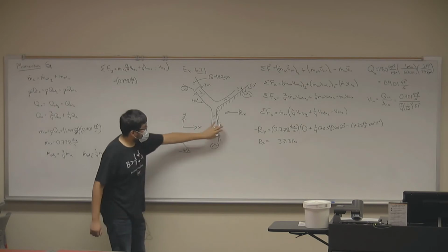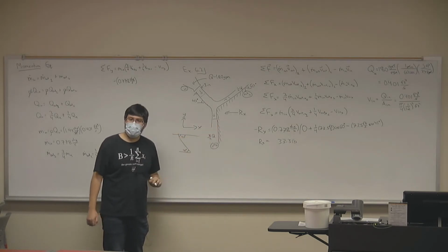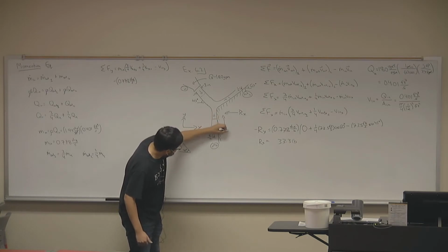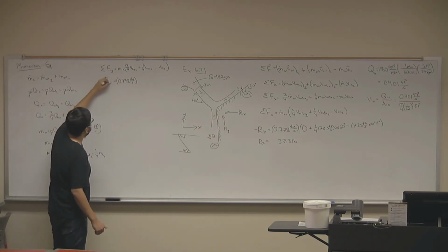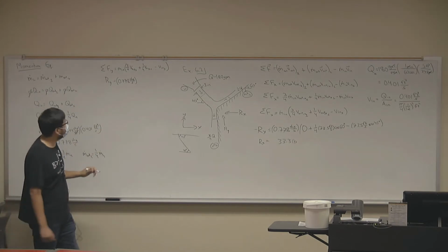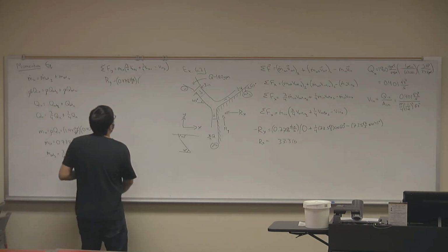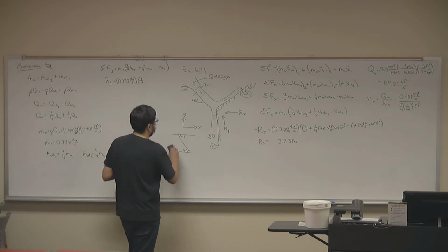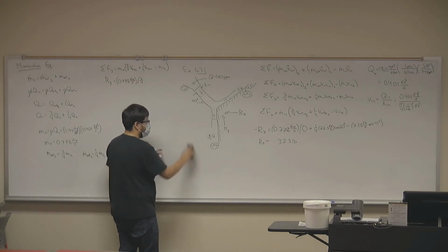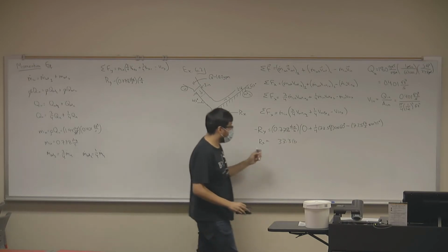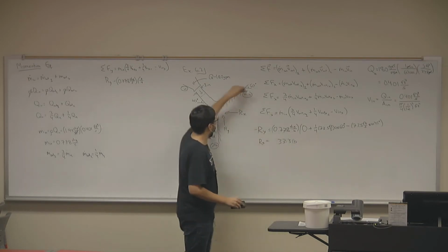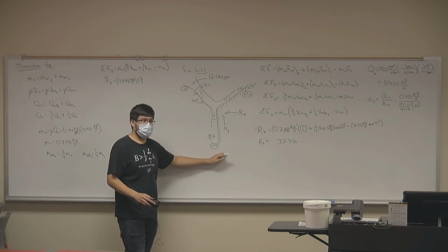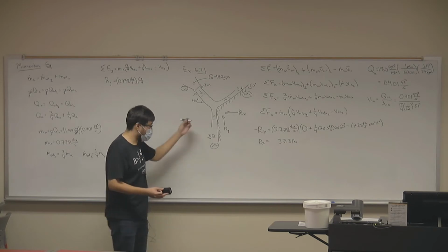In which direction do you think the y resistance is acting? Upwards? Okay. So Rami guesses that it's upwards. We'll see if Rami is correct or incorrect. Because it's upwards, I'm going to leave this as a positive value. All this multiplied by 3/4 of the y component of the velocity leaving the system through outlet number 1. The velocity is 73.5, the magnitude. So what is the y component of this velocity? All of it, right? 73.5.